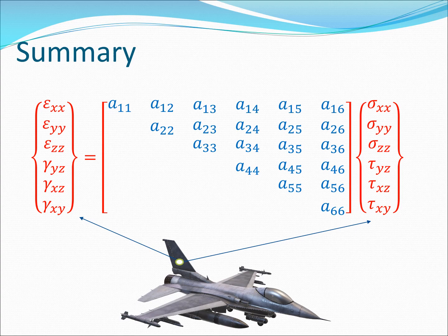So what is going to happen is that these stresses or strains are going to lead us to failure theory, because the failure theory uses certain concepts like principal stresses, maximum shear stress, and so on, and those all come from knowledge of the stress matrix or the stress vector. So once you know the stress state, you can very easily calculate the principal stresses, and then you can work with failure criteria such as the Tresca failure criterion, the von Mises failure criterion, and so on.